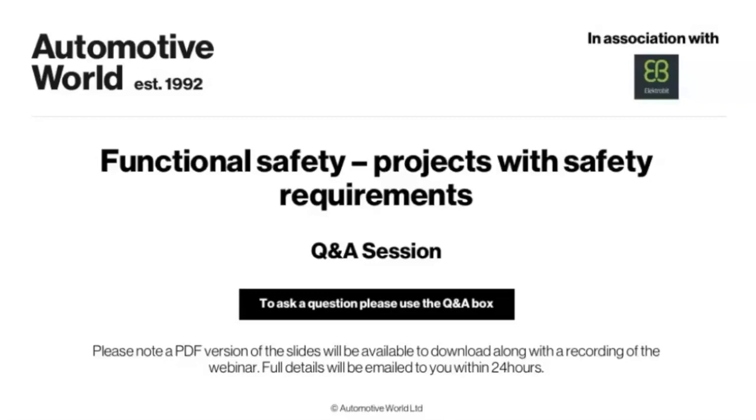In one of your slides, you explained a mixed type of both QM and safety. Can you explain this concept with the help of application requirements? The person who sent the question says that, according to their understanding, QM has no safety requirement. That's correct. The integrity level is assigned to the requirements, not to the function.